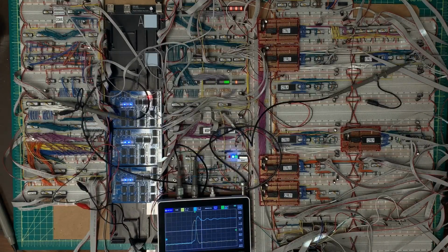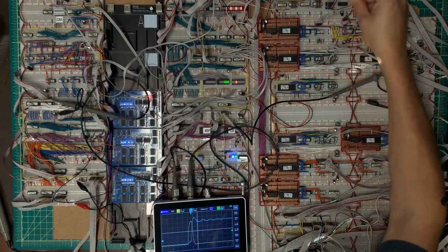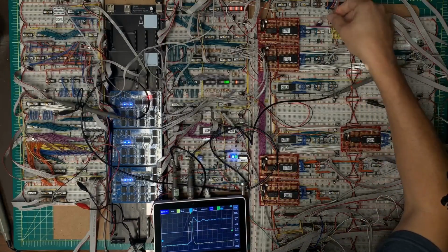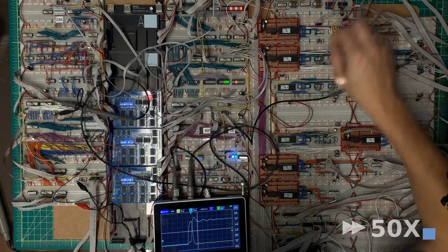It's almost like I still need to shift that spike clock to be later, because if the load ends about here and the latch takes place about there, I need to shift that spike clock to the right a little bit. So I do then need to add an additional delay in here.